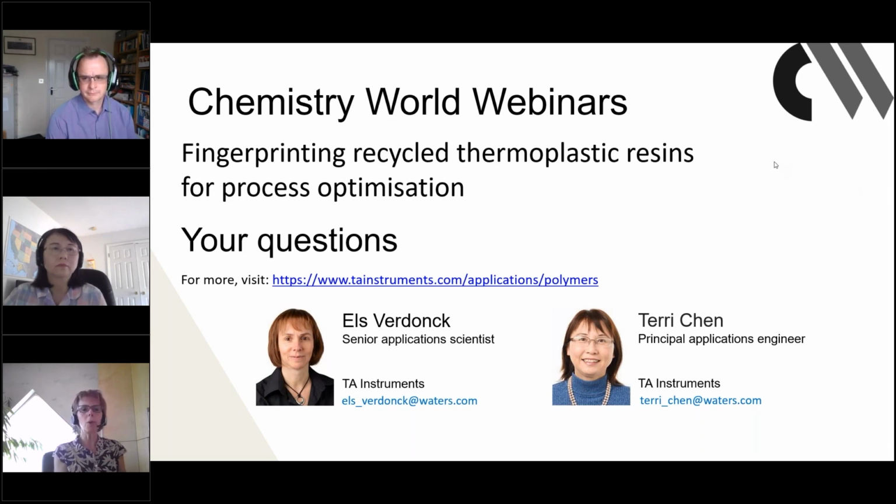Now, if you do the processing at a temperature very close to the start of decomposition, then the decomposition will go very fast. And then you could indeed make your life easier. Instead of doing that kinetics, you could just make a measurement where you keep your material for some time isothermally in the TGA and watch how long it takes before it starts degrading. And this is then only one single test.